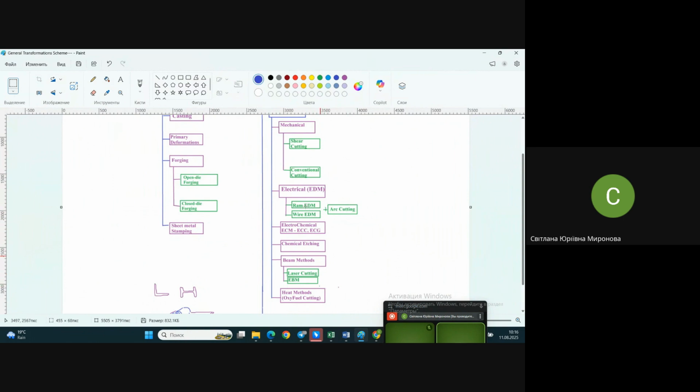But both of them, in contrast to conventional cutting, are able to produce practically zero radii, straight corners. Conventional milling doesn't offer such an option. But for shear cutting, it's already available. But shear cutting works only with thin materials. Sheet, maximum plate, maybe in some cases. Sheet, profile, pipe, yes, shear cutting is for it. But not for complex spatial shapes. Okay, let's come back to our slides.